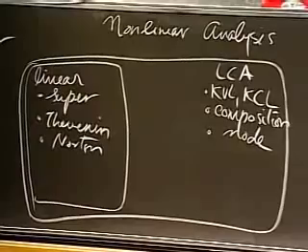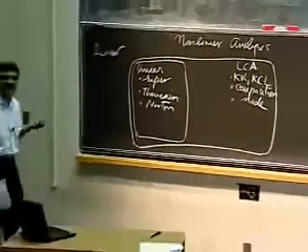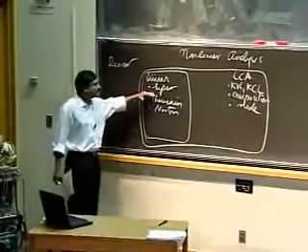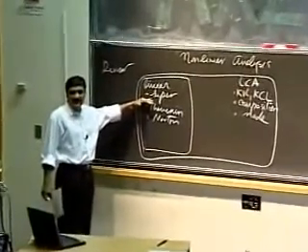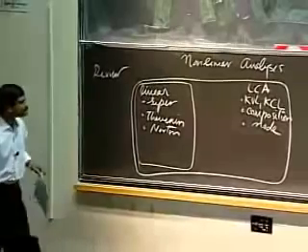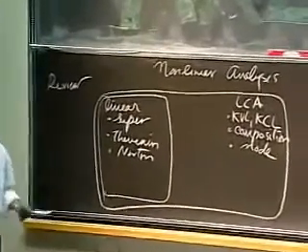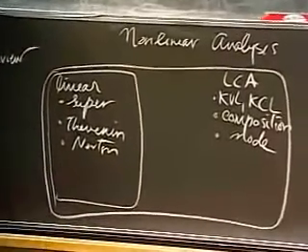If you see a circuit containing 2 or more voltage sources or current sources, as a first step, think superposition. Okay? And these are very powerful techniques that let you analyze very complicated circuits very effectively.